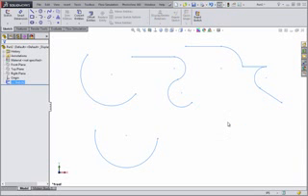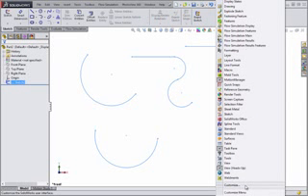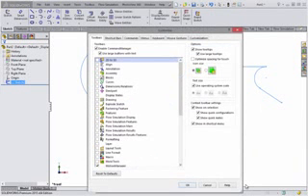You can add up to 8 gestures for a given environment, and can fully customize which commands are displayed. To do so, right-click on a blank spot in the Command Manager and select Customize. Then access the Mouse Gestures tab and set as desired.